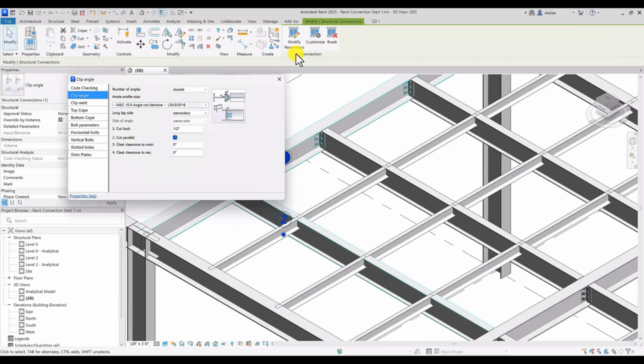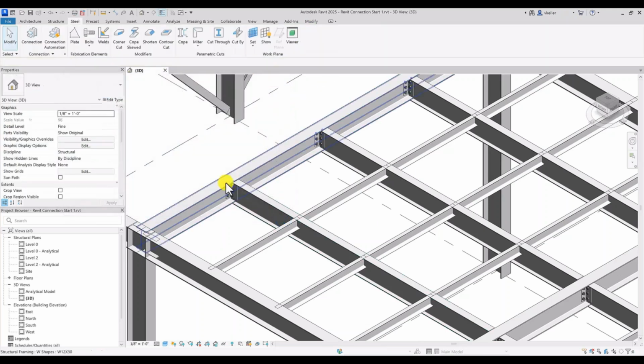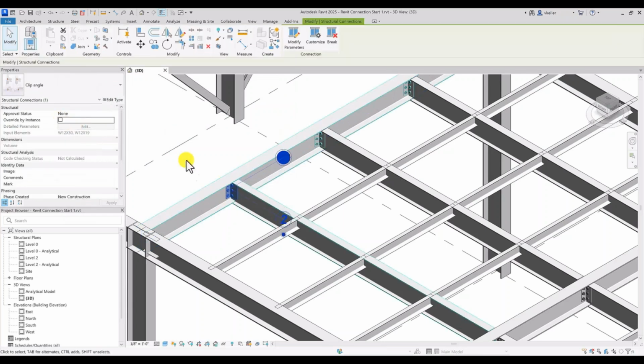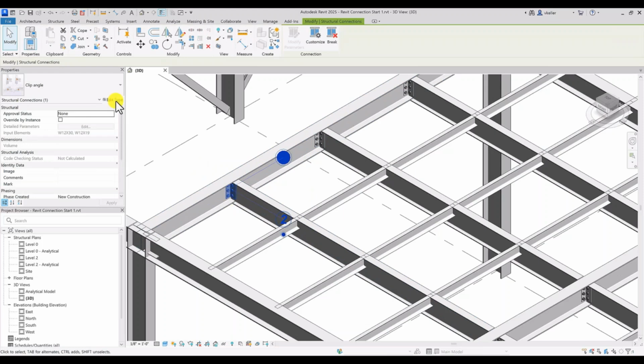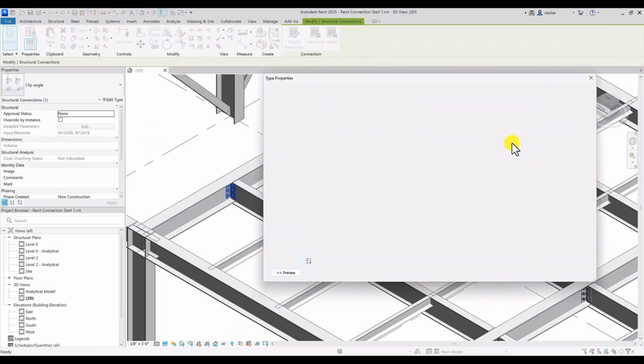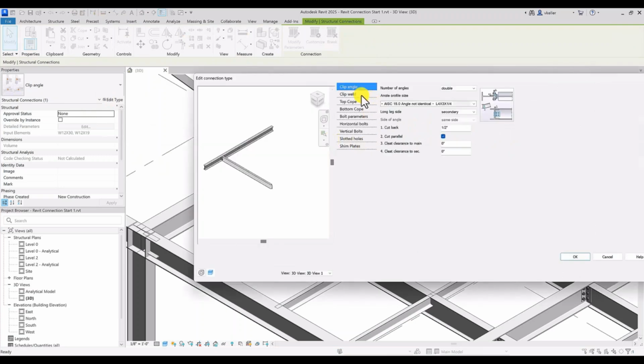I'll make it real obvious. Obviously that's changed. Now, if I want to put it back to everything else, then I uncheck instance and it's back to the other ones. So you can override what is called the instance and properties if that's what I want. Through here, it's global update, type properties. Make a change to one, they all change together.